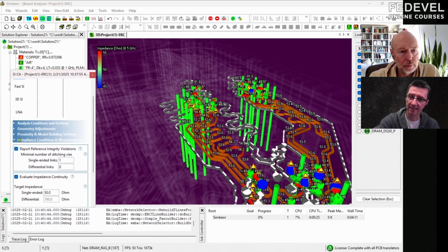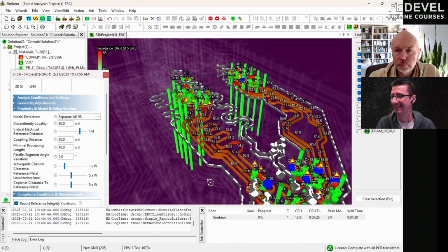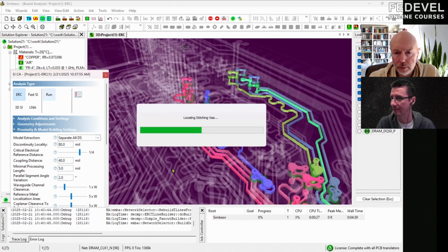That's the second bank, but it's routed a little bit further. You can even see it. These tracks are a little bit further than the other tracks. So we put some larger distance for crosstalk here to basically improve the accuracy of analysis. Let's just put 5 mil. Okay, and click run, and we'll see the crosstalk.